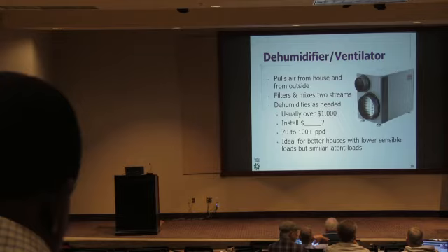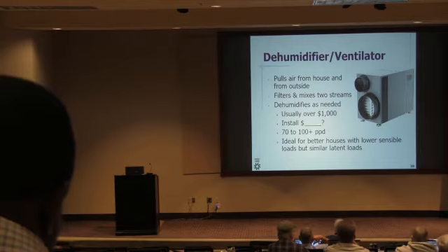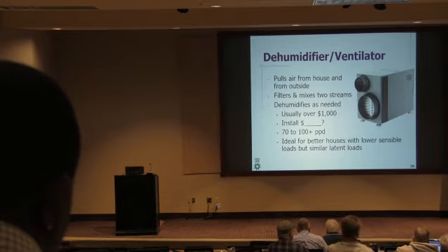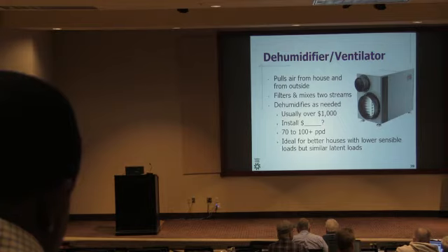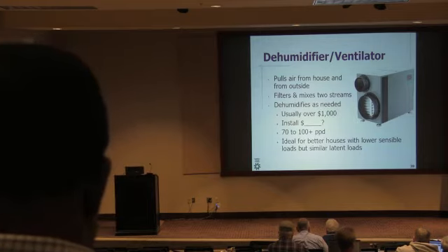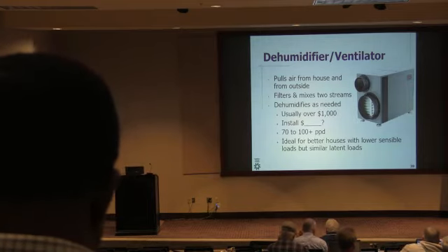Is it looking at fresh air or is it looking at humidification? Depending on how, I think these are typically ducted in with the duct system of the house, so they would probably pull some return and provide you some dehumidification of the inside air, but primarily they're trying to dehumidify the outside air. I feel like you can have both. You can have it standalone, where it was just dehumidifying outside air, but if you're pulling any return from the house, it would dehumidify that as well.